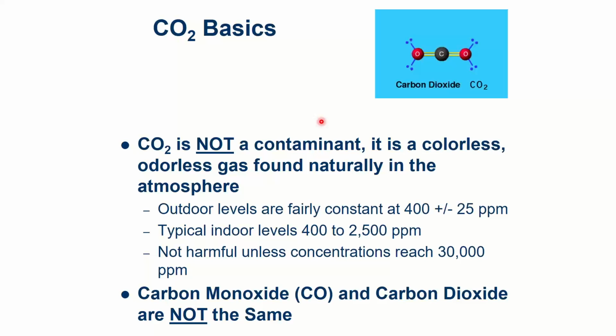I say this because I can't tell you how many sets of blueprints I look at that call for carbon monoxide detectors in an office building. And I'm like, but you guys have a heat pump with electric heat. You don't even have anything doing combustion. Why is there a carbon monoxide detector? Like, we want to do that ventilation thing you talked about. Well, time out. You meant CO2. That little 2 is important on there. It's a big difference.